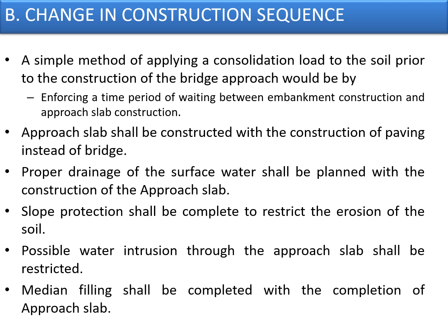So quite possibly a cavity can be formed from the median, which may run across the cross section of the road to the edge. So the cavity which is formed from the center of the road to the edges of the road will cause the approach slab to settle. So it is required to fill all the gaps which are being covered with the approach slab with rigid materials.